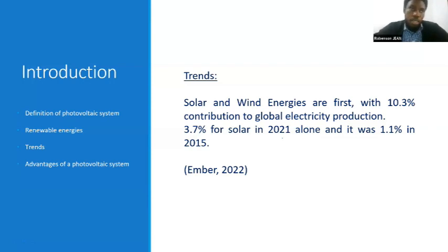So if I give it 10 volts at the input, the output will be 15 volts. If I give it 100 volts at the input, the output will be 150. So the most important thing is not the input voltage or the output voltage, it is the ratio. But there's also a range of voltage that we can use for a given DC-DC converter.